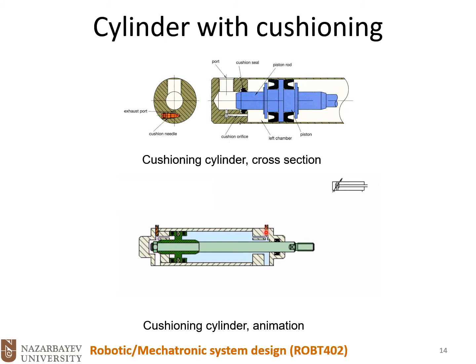What are these small set screws here and the orifice here? This orifice basically helps us to adjust the degree of cushioning. If we open it completely, this opening, the air could easily move from this vent outside and be exhausted easily, and the level of cushioning will be very low.